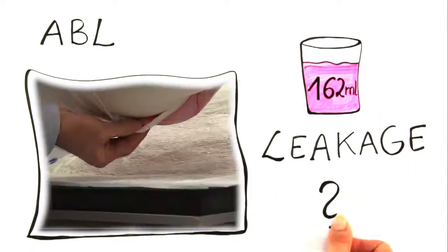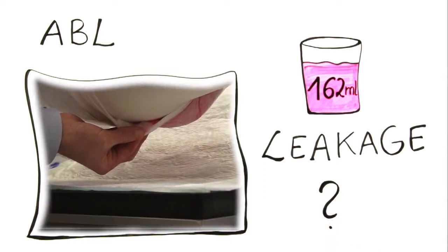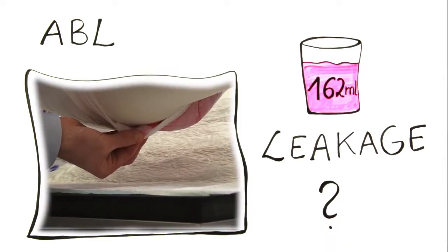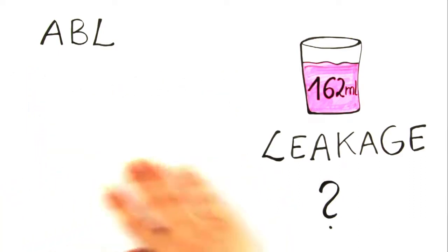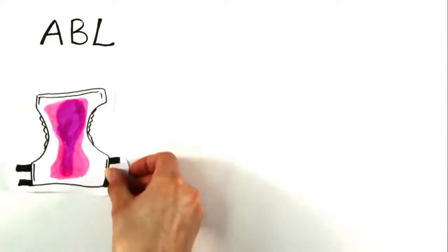After a defined time, the diaper is tested for leakage. If there are no drops coming out of the diaper, we continue to add the solution until a leakage is observed. As we can see, the urine substitute solution collects mainly in the rear part of the diaper. Next, we weigh the wet product.